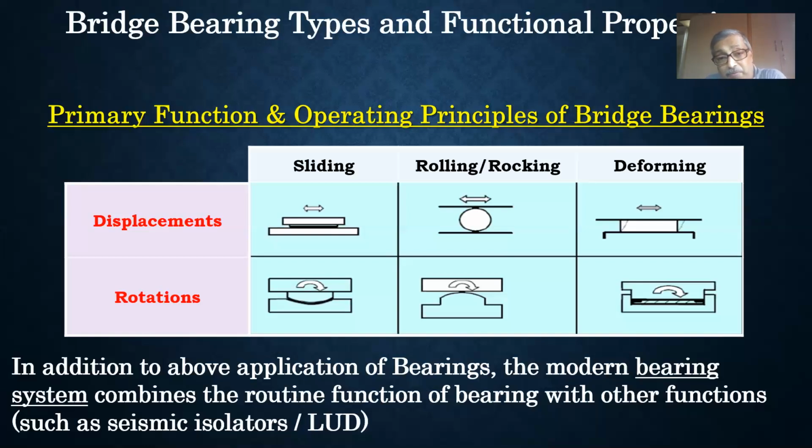The third method is by deformation, which is a concept used in the case of elastomeric bearings, where the top moves with respect to the bottom, and thereby there is a shear deformation. And this kind of deformation will attract some force to the substructure and foundation, but the elastomeric bearings being quite flexible, these forces are catered for in the design, but they are not significant.